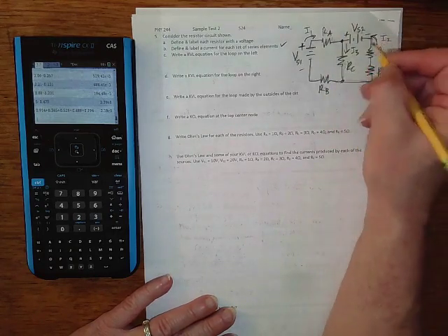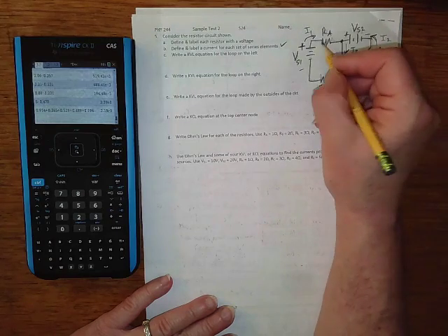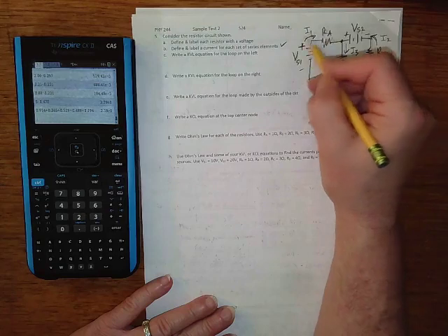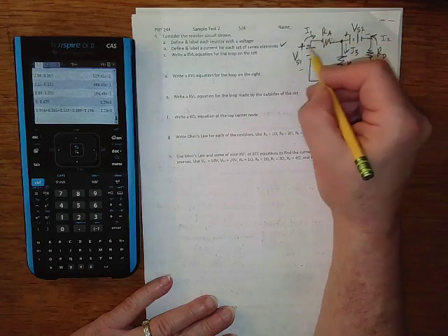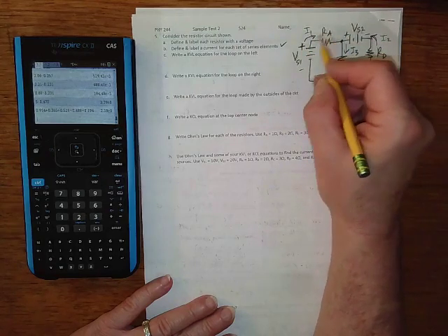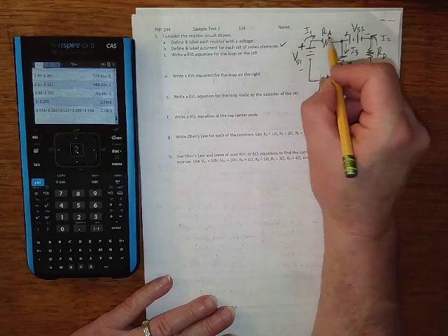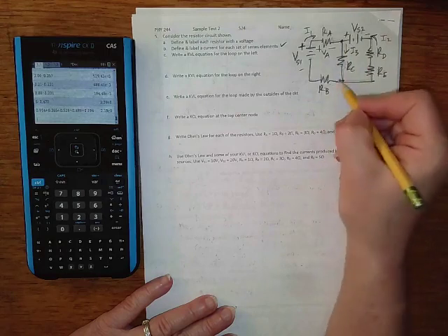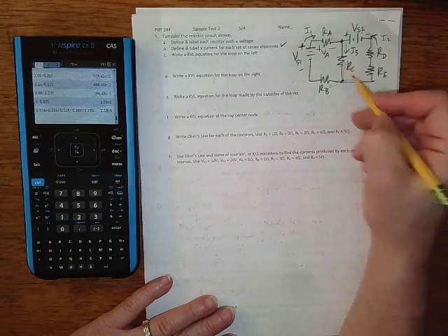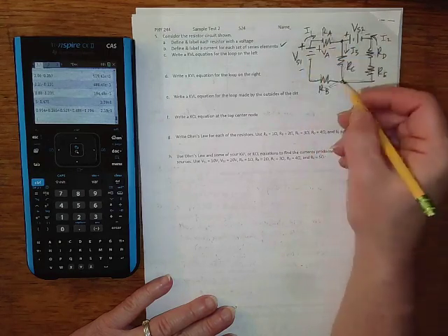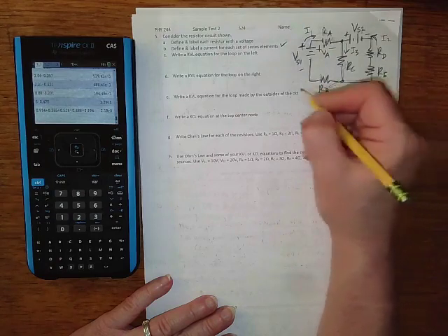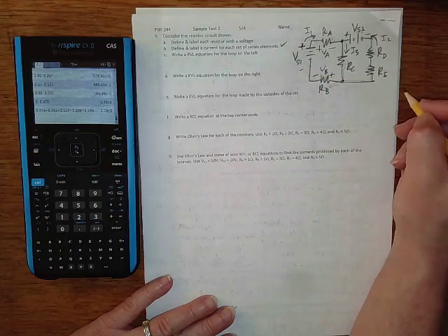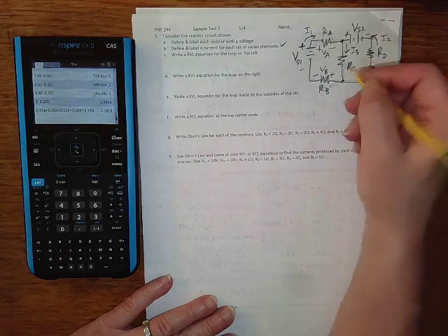And now let's define the voltages on the resistors. For resistors, positive happens when current comes into the plus. So we want the plus to be the side where the current's entering RA, for example. It's entering from the left, so that's going to be the plus. I'll call that VA. Down here, I1 is actually going this way, right? So it's coming in the right-hand side. So let's put the plus there. Name it VB that way.